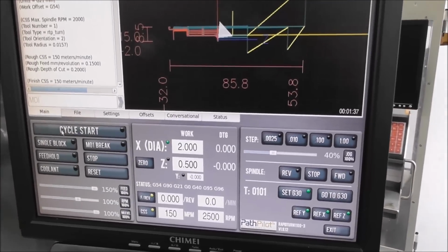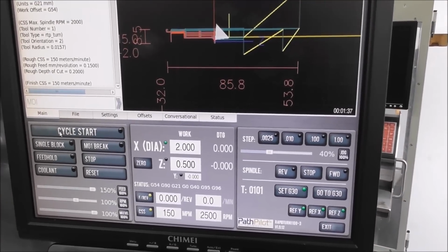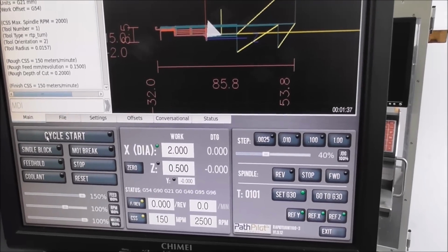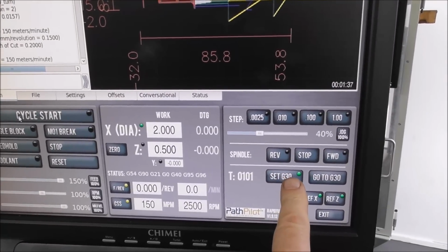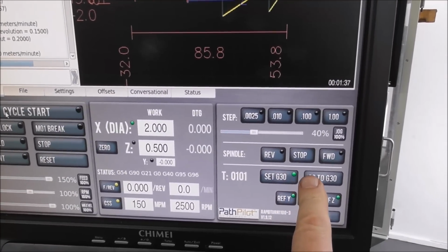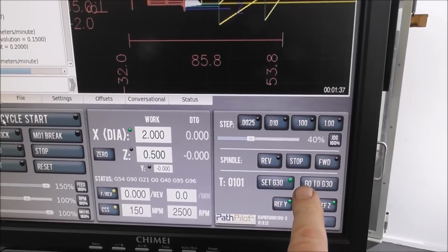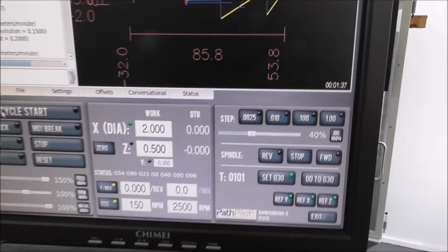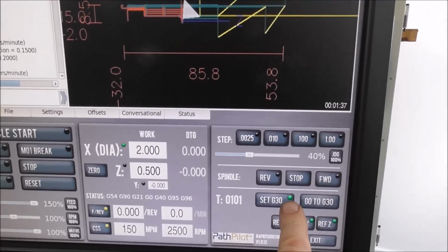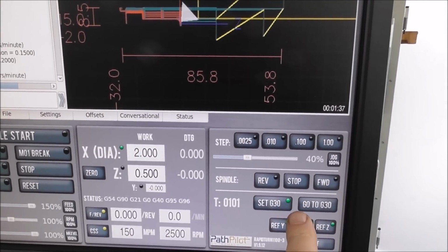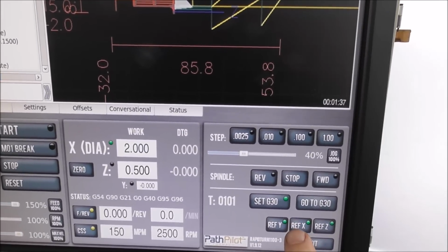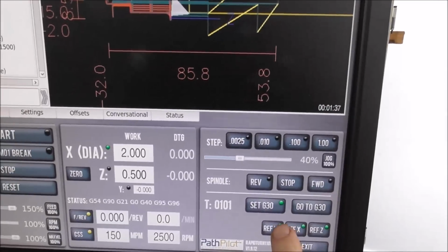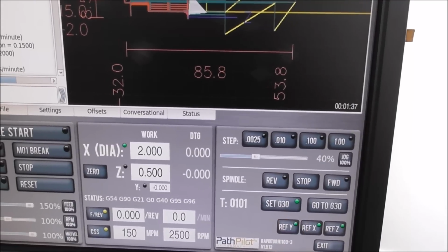If you do decide to use the fresh air machining method to check your tool path out, remember to set your G30, that's the tool park position, back beyond that temporary position temporarily. That's only an approximate position, but you don't want to have your tool rapidturning in towards the chuck during the tool park maneuver, and then you can put it back to about where it was when you finish testing it in fresh air.